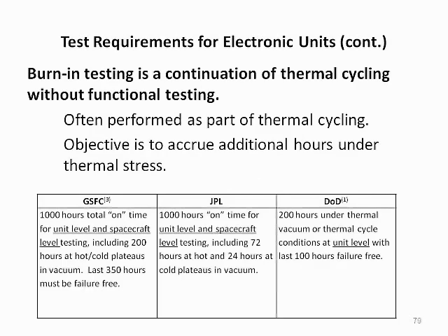Most organizations have requirements for burn-in testing, which is a continuation of thermal cycling, but without functional testing. It is often performed as part of thermal cycling with the objective of accruing additional hours of operation under thermal stress. Each organization has different specific requirements for total burn-in time, at what level the burn-in must occur, and how many failure-free hours must be demonstrated.